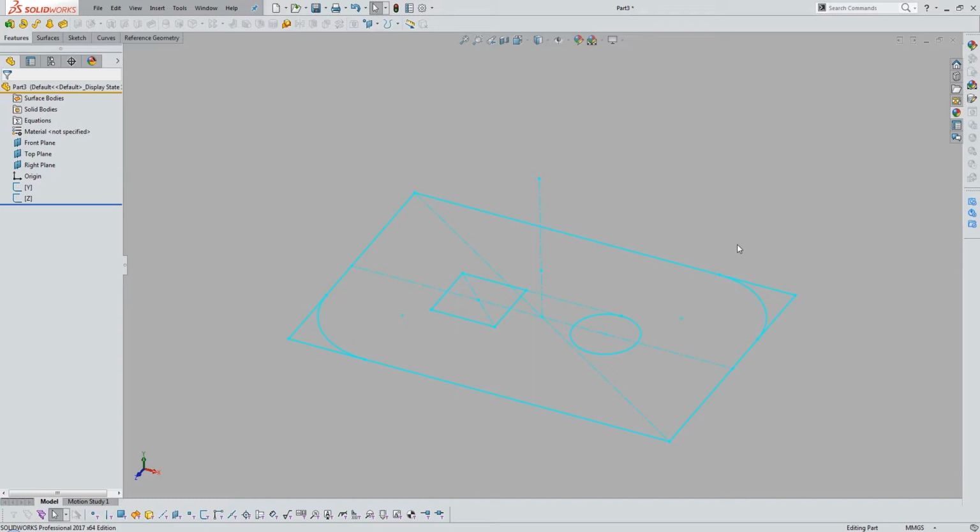This part has to exist in real life. It's made out of a rigid material, and it's going into a mold that can't deform. It's not squishy enough to get out of the way. So we have to make sure our part doesn't get stuck in there. And thinking like a mold, thinking like the tool, is the best guide for knowing how to draft your part. And then knowing which drafting tools to use, that'll just help guide your modeling flow. But your eyes on the prize is to be able to get this thing out of some injection molded tooling.